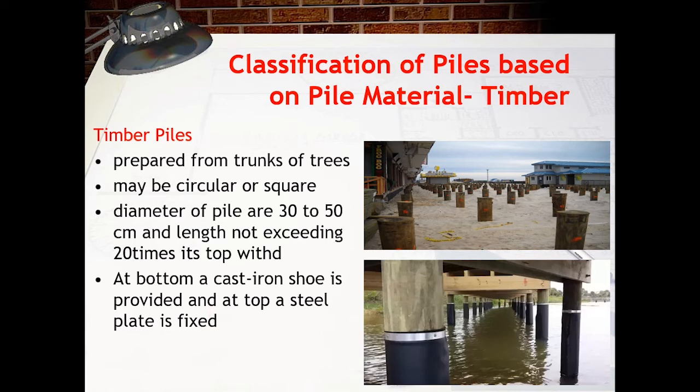Timber is a relatively inexpensive material to be used in construction, and its durability against rotting can be improved using preservatives and advanced techniques that are available in the market. However, the main drawback of timber piles is the limited structural capacity and length. Hence, timber piles are most suitable for construction of residential buildings in marshy areas and for stabilization of slopes.